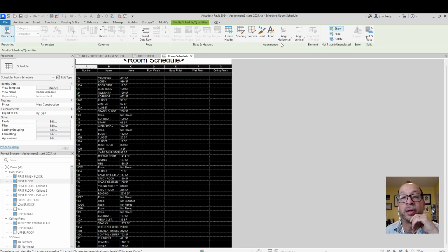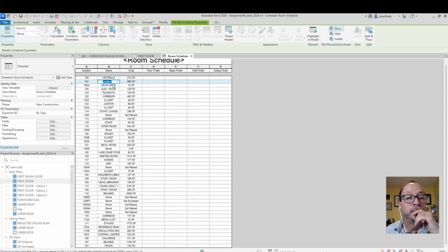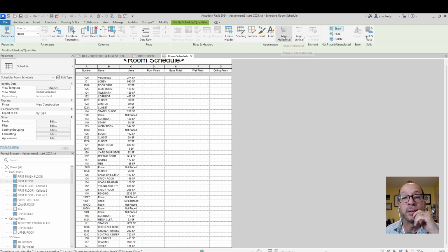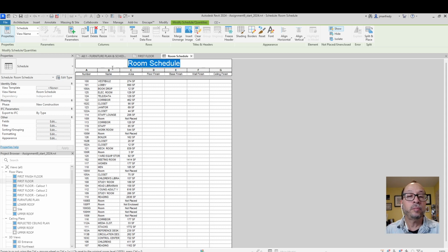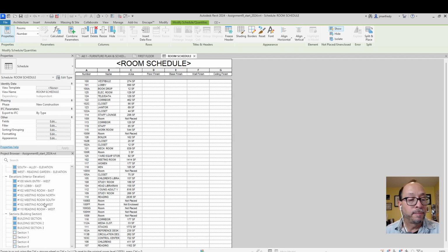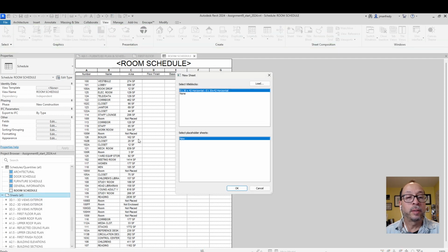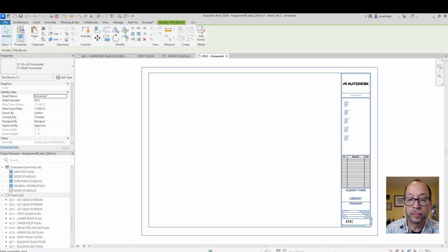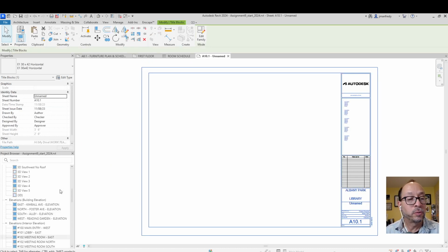And you're probably going to want to grab everything here, center it. Unless you want to make this left justified for the names, it's up to you. And grab the title there and make the title itself centered. And then the rest is up to you all to manipulate. Room schedule. Again, you can make this list appear on a sheet. I right click. I'll make a sheet called A10.1 and just grab the room finish schedule and drop it off. So here, room schedule, drop it off.